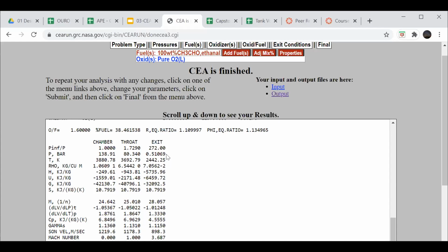or below, because, as Jackson was saying, you can break the nozzle. The nozzle will try to expand the gases out of it, but then they'll start collapsing back inwards because the exterior pressure is larger than what the nozzle is trying to expand it to. You'll have the flow break away from the wall of the nozzle, and then you'll have weird oscillations and shock waves. Gotcha. So how does it not do that at slightly below atmospheric? It does. It's just not a large enough effect there. It doesn't break away until it's already pretty much at the end. Gotcha.